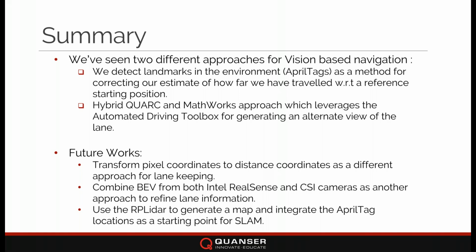I'm leveraging the Computer Vision Toolbox in order to generate what my camera sensor properties are. I can save that. It's powerful because I can now define my sensor at a bunch of different resolutions depending on what I would like to do. Lower resolutions maybe give me a faster frame rate, which is useful the faster I go. But if I'm more interested in picking out the details in the environment, maybe I want to do some object detection just using the camera from a bird's eye view, I may be interested in a higher resolution image, but not being acquired as fast. And so I can see what that trade-off looks like.